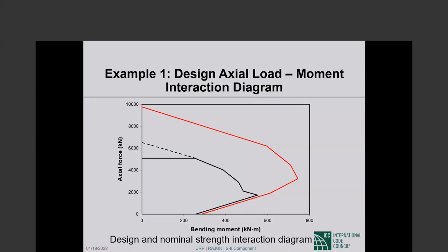I do not know a direct answer, but a column is under compression almost always. If a column has cracked, there is a problem. So it has been subject to tension for some reason. I would rather figure out what happened than try to figure out the capacity that may remain. So spalling indicates high compression. I think rusting also leads to spalling. Well, yes, rusting does lead to spalling.